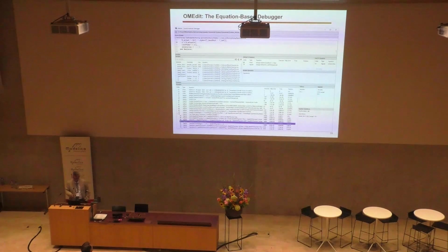This is an output from the equation-based debugger. Now, this is a problem. The equation-based debugger needs an 8K screen. The larger, the better. I'm not sure if you can read, but what you see here is the sequence of computations which is carried out on the generated code. That's more or less what you see in the dsmodel.mof file of Dymola, for those of you who are familiar with it. Here you see the last three initial equations, which actually turn out to be asserts.